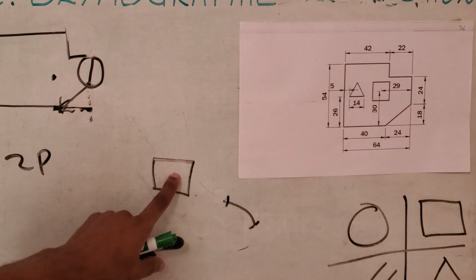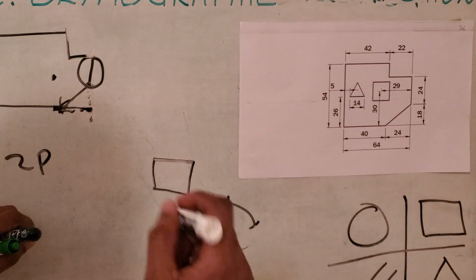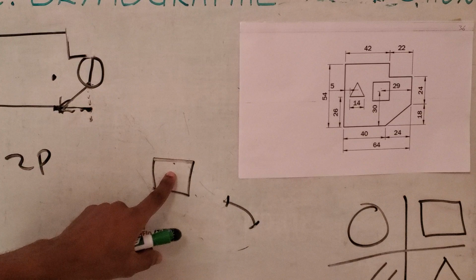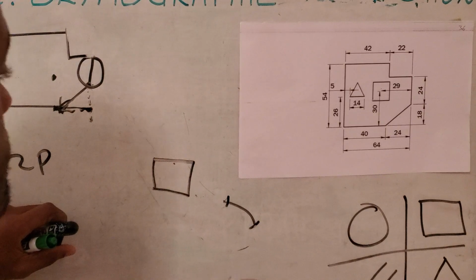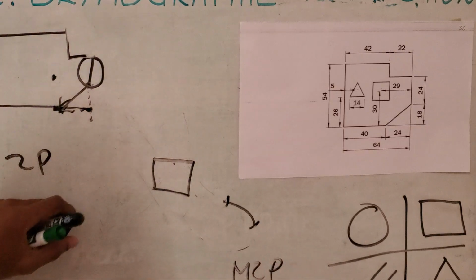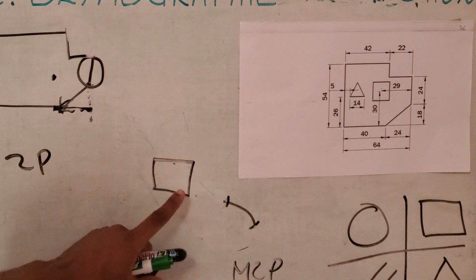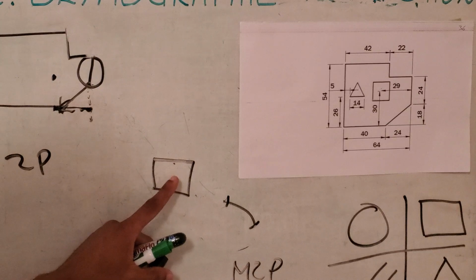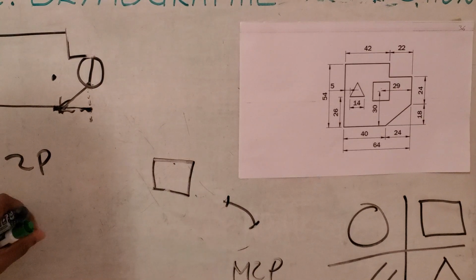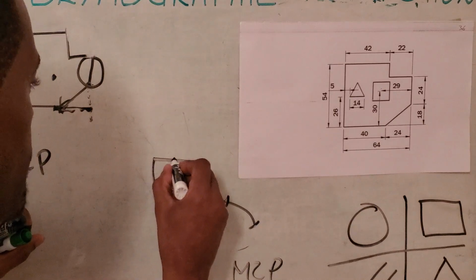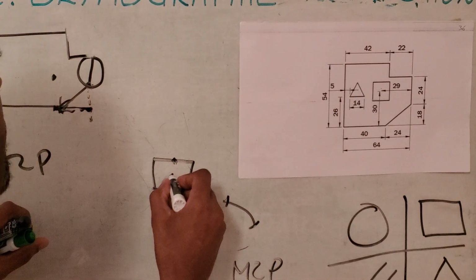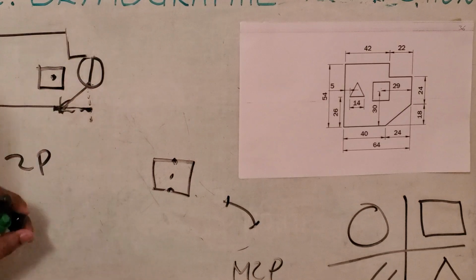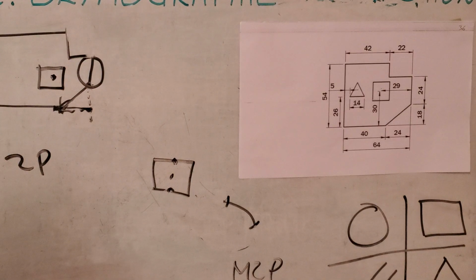We then move this from here to here. In this case, you might not be able to snap onto the center. What you can do is turn on center. Or if you don't have that, you could use M2P, middle of 2 points. M for move, then click on the object to move. When the command bar asks you to specify the base point, you type middle of 2 points or M2P. Then you click here as 1 point, click here, and it will automatically select the middle. Then you drag and drop it right here to get that. That is now done.